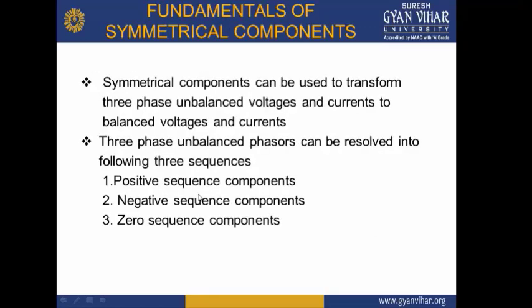Now, let's discuss some of the fundamentals of symmetrical components. Symmetrical components can be used to transform three-phase unbalanced voltages and currents to balanced voltages and currents. That means we have a balanced system and due to some conditions it becomes unbalanced. To do the analysis, it is always preferred to work on a balanced system. It would be a very complex and tedious task to do the analysis on the unbalanced system.